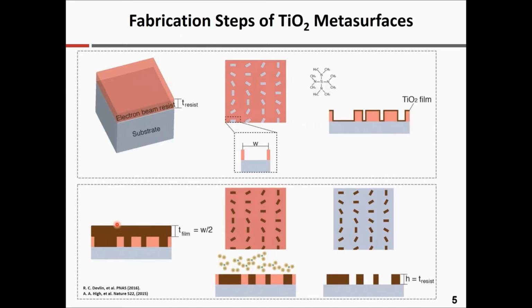The next step is critical. So you will etch back to expose the resist and lift it off. The etching here does not define the structure, but is just to expose the resist to have a high quality structure, which is a complement of our resist with the same height.